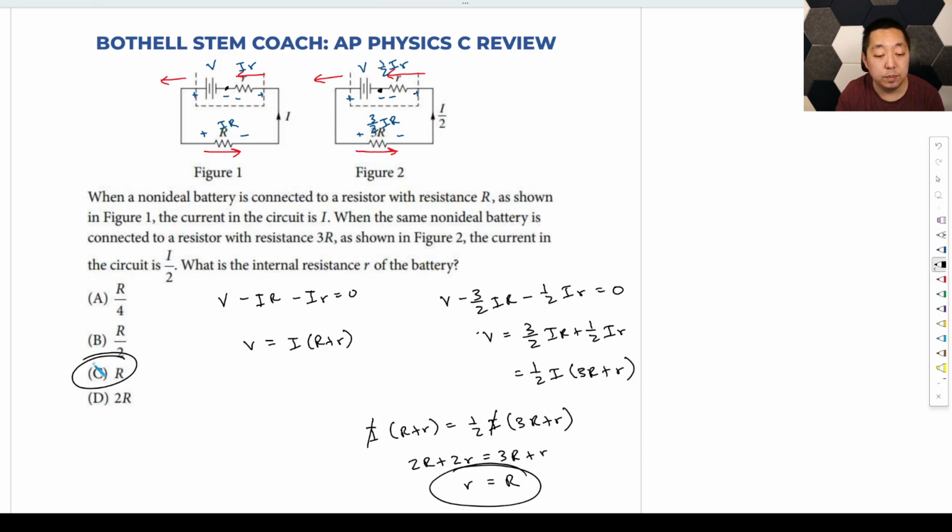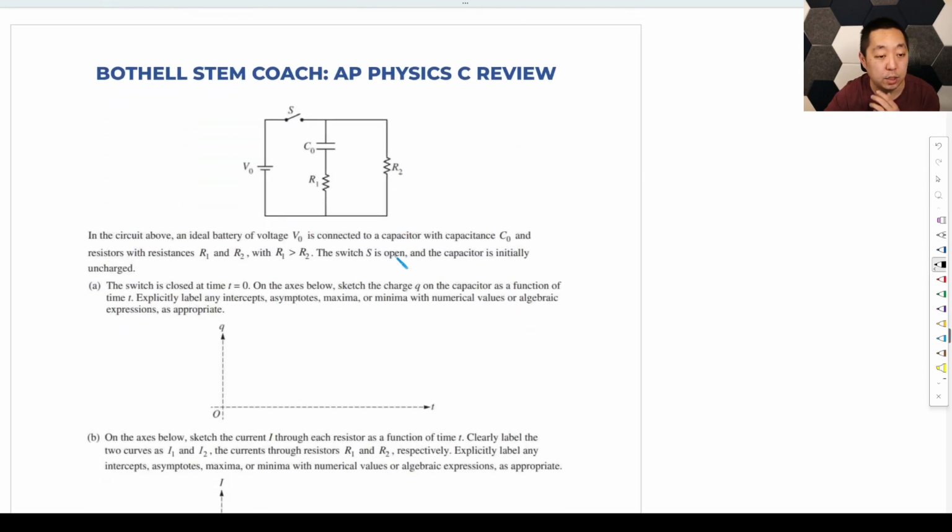Okay, so that is how you can do it. You can do it with series and parallel collapsing as well. But I wanted to do that to illustrate that this is the circuit analysis process for resistors. That is the process you follow. You can collapse them, sure, and that would have worked in this problem, but it doesn't work in all problems, which is why it's not always a thing you want to just automatically do.